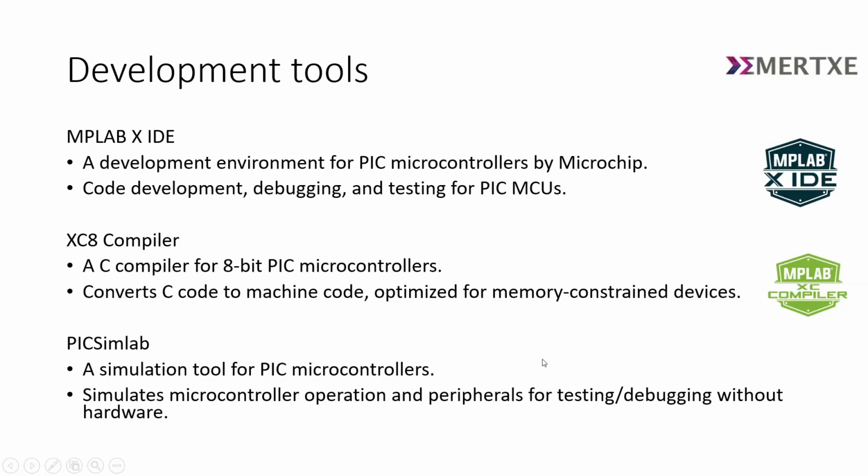Next we go to development tools. What we have used: MPLAB X IDE, that is MPLAB integrated development environment, developed by Microchip. Next is XC8 Compiler, a C compiler for 8-bit PIC microcontrollers that converts the C code to machine code. Next we have PICSimLab, a simulation tool for PIC microcontrollers that simulates the real-time environment similar to the washing machine.